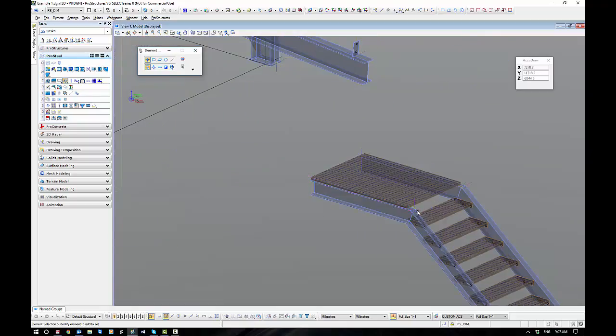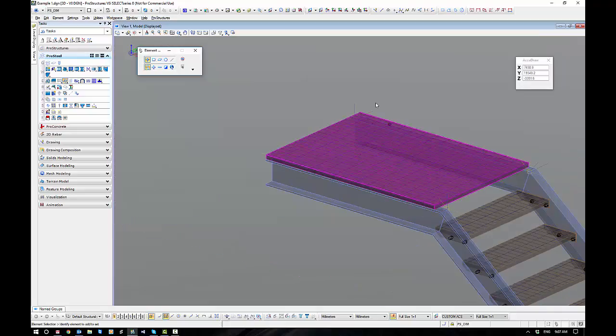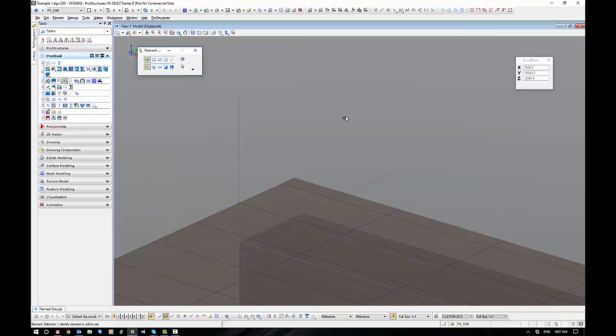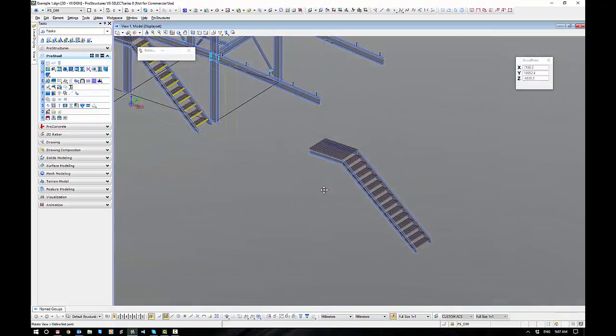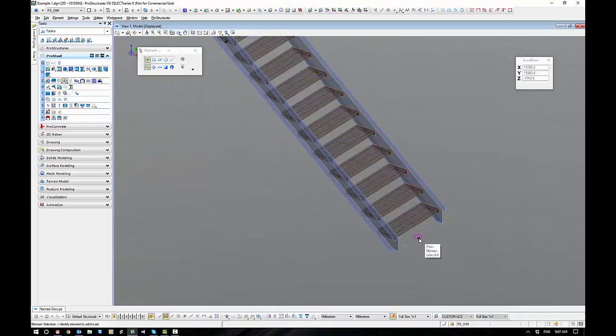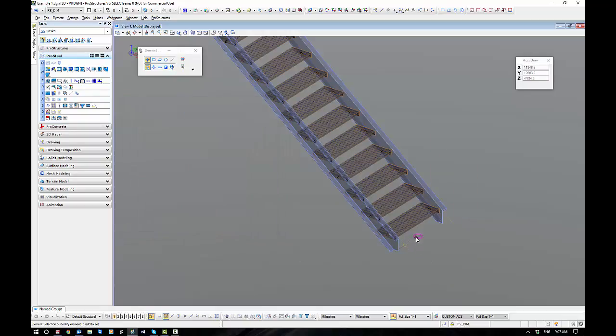And the final thing, the nice thing about it is if we have a look at the ECS axes there, the blue line is up, top of steel is top of steel, and this guy over here, blue line is up also, which means connecting them is a piece of cake. Final thing, editing is this little circle. There's no box, it's that little circle. So if I select, right click, go to the properties of that circle, it is my stair function for editing.